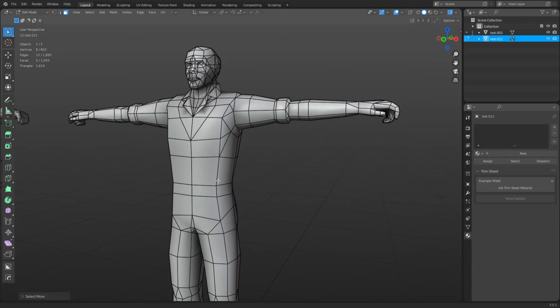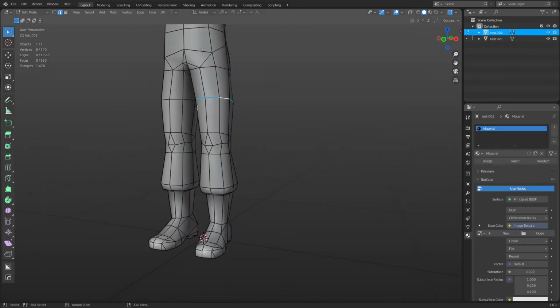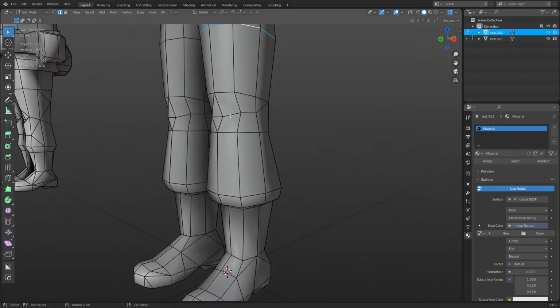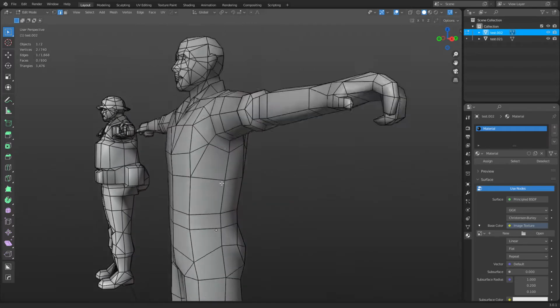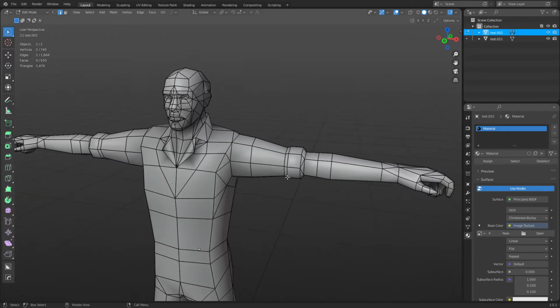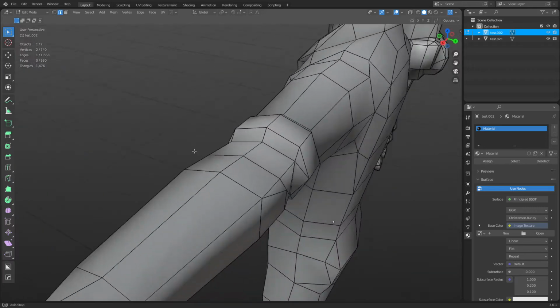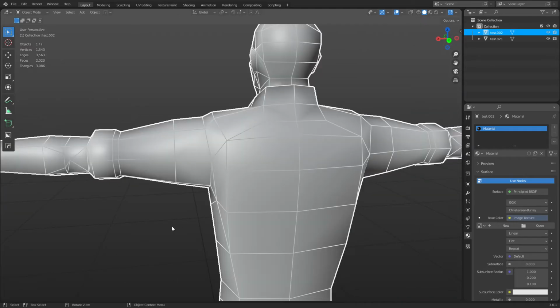Nothing crazy. This guy, even more simple. The segments around the leg here, it's basically an 8-sided cylinder. And you might have to do a little fancy work for the kneecaps, maybe a little bit for the footwork down here. But generally speaking, if you make a character all out of quads and you keep it really, really simple like this and only focus on having the extra geometry where you need to bend the elbows and things like that, you can take a look at these reference characters on ghostrecon.net, download them, and then take a look at how they're made.